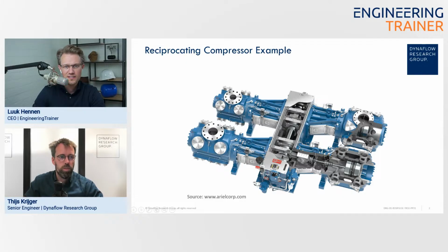So there are different parts. What you see on this screen is, for example, a four throw compressor. So it has 4 of these connected pistons. But this kind of system can have 6, 1, 2. There's also one. It doesn't have to be evened out on either side. It is possible to make a single cylinder, but the forces that are acting on your crank axis will be more difficult. But they do exist.